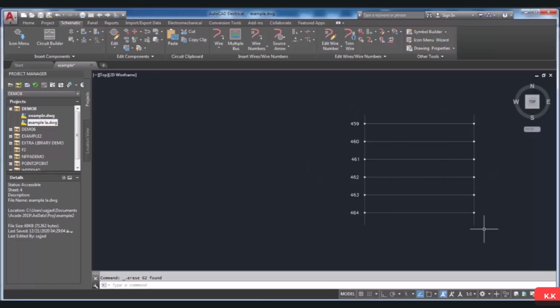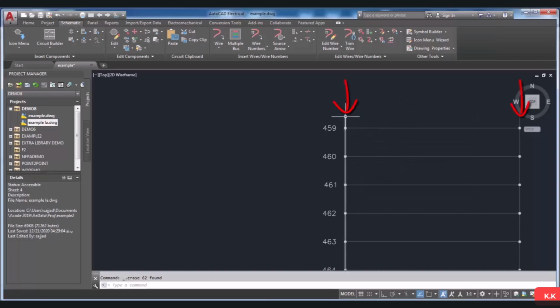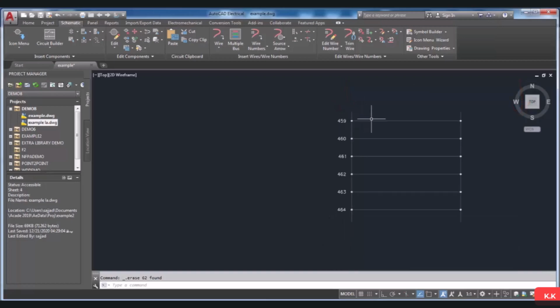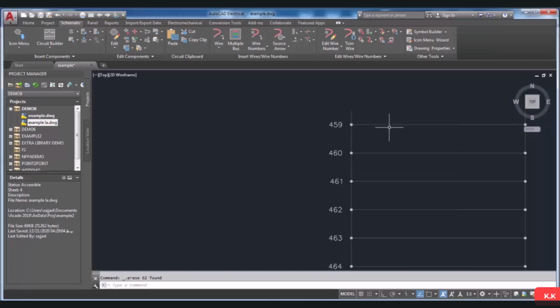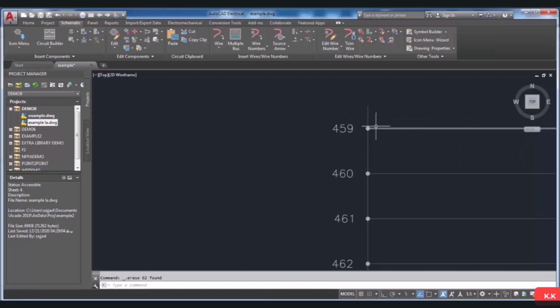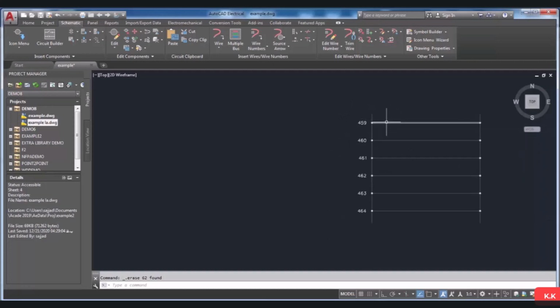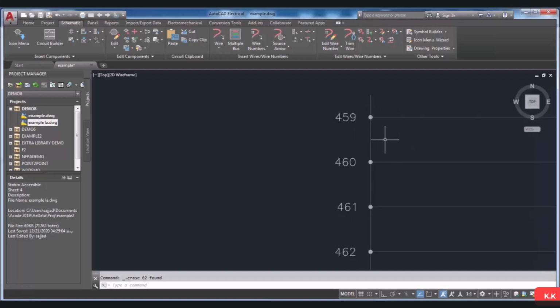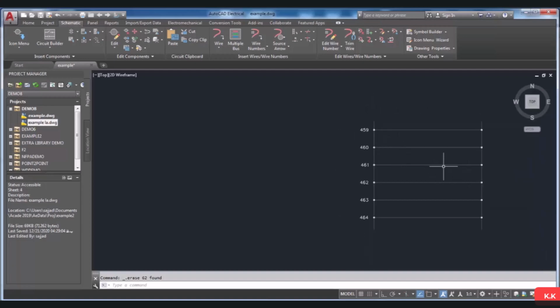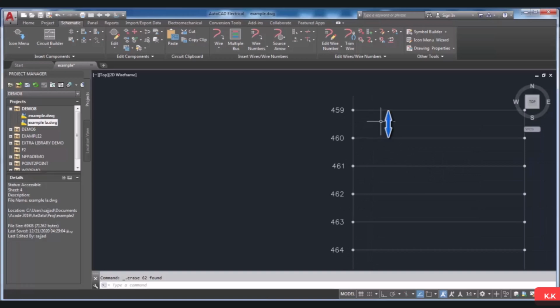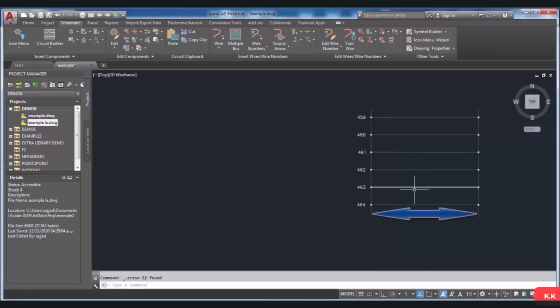I have prepared a drawing that includes a ladder, and here you can see it. These two vertical rails work as a supply and are named buses, and the horizontal lines are called rungs. Each intersection of horizontal and vertical lines, I mean rails and rungs, expresses the reference numbers. The distance between the rungs is called rung spacing, and the distance between the rails is named width.